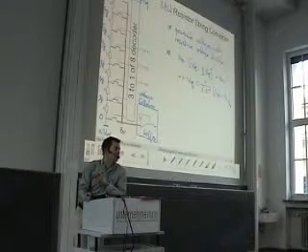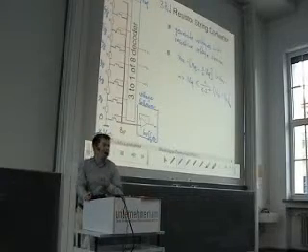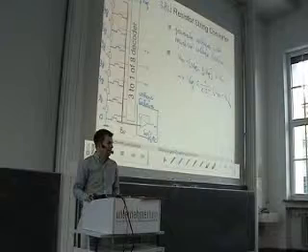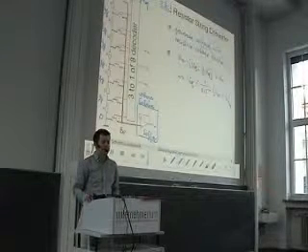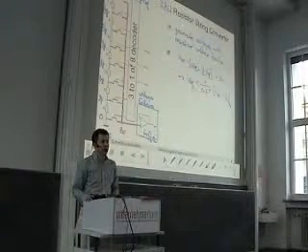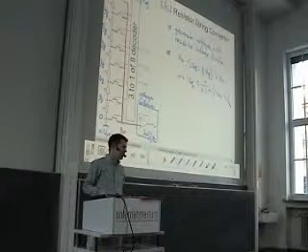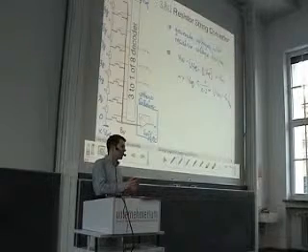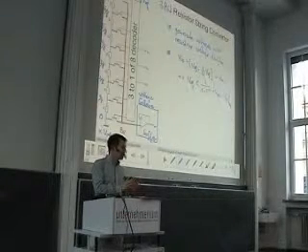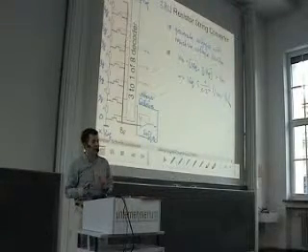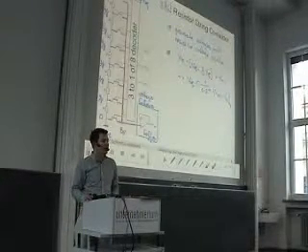What can we do if we want to go for a higher voltage range? I guess we discussed this when we talked about MOS transistors as switches. There we saw that the NMOS transistor is a good device to switch small voltages. A PMOS transistor on the other side is a good device to switch high voltages.